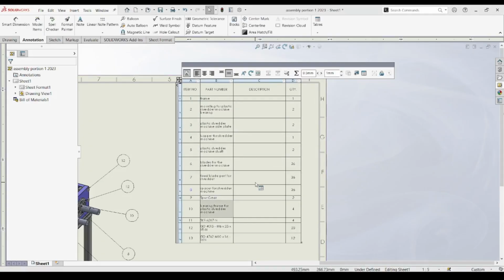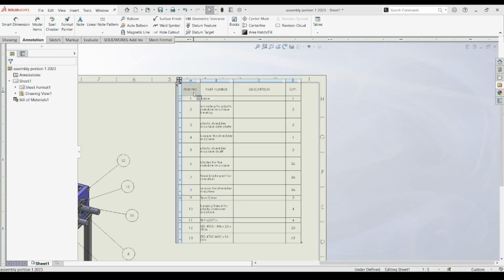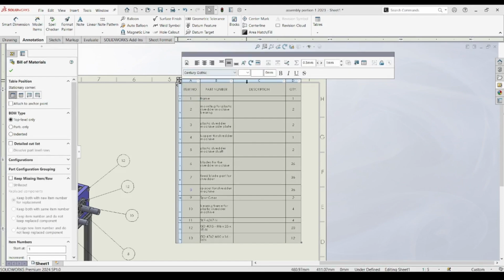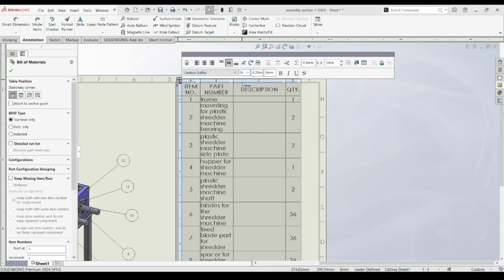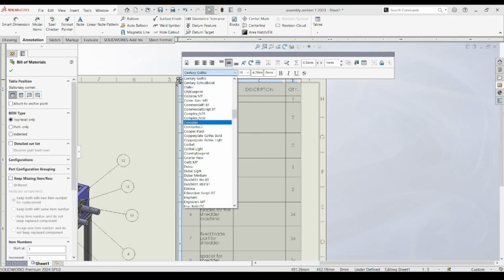For example, when selecting bolts from the SolidWorks design library, each ISO standard fastener comes preloaded with critical metadata. If you've been following along from Part 18, where we added fasteners into the mounting and side plates, you'll see how those parts now show up in the BOM with size designations, standard numbers, and quantities, all without additional manual input. This level of automation cuts down hours of administrative work while improving accuracy.